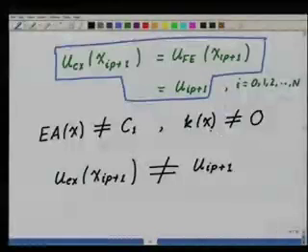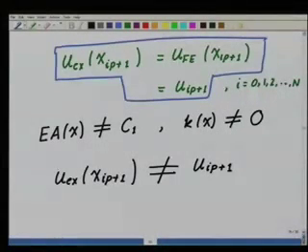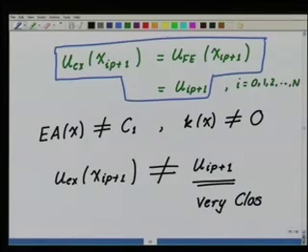Remember that in the case of a bar with a variable cross section or with a variable material or a bar with all of these and/or these actual springs, this is not going to be true. However, is everything lost? No. It is not going to be true, but this will be very close to the exact solution. This is a feature of the finite element solution that is again unique to the one-dimensional problem that we are talking about. We will not be able to generalize it to 2 and 3 dimensions. But nevertheless, this is a very nice property of the solution.